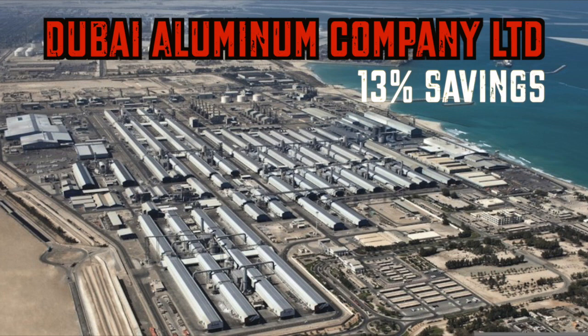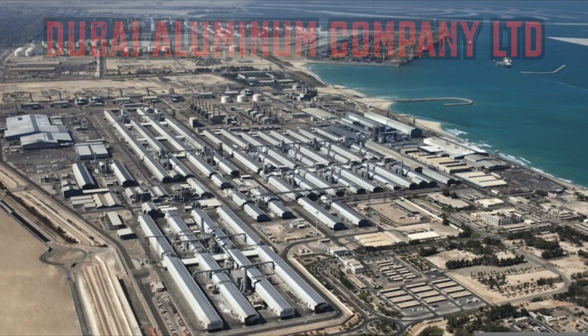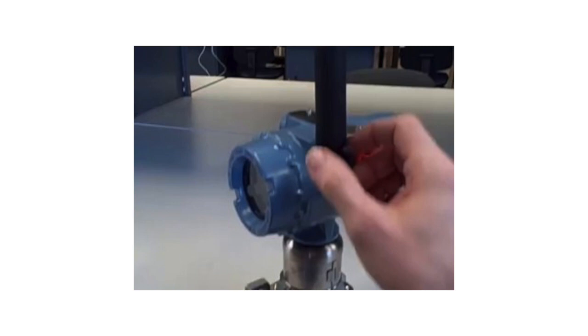They did it by connecting wireless transmitters to flow meters that they already had installed in their system. They installed 20 of these wireless transmitters, which then organized themselves in a network. And because the sensors themselves were already in place, they were able to install wireless communication parts on top of the sensors without much impact. It only took about 15 to 20 minutes to install each individual communication node.